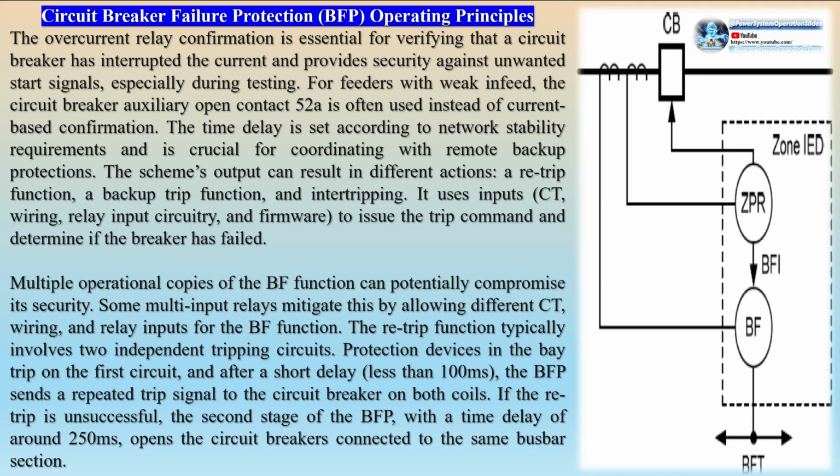There are several ways to utilize distance protection. Zone 2: employing Zone 2 of distance protection from the opposite end of overhead lines or underground cables. Reverse zone: using a reverse zone oriented towards the busbar for transformer or overhead line distance protection. Coupling circuit breaker: utilizing distance protection to trip the coupling circuit breaker, with a blocking scheme between distance protections in a ring substation topology.